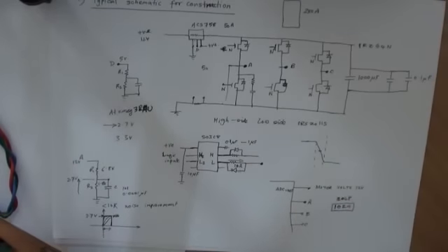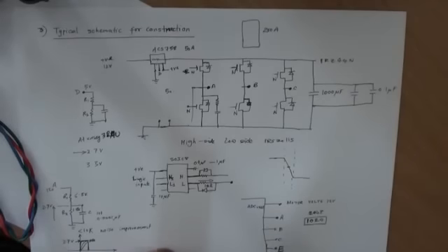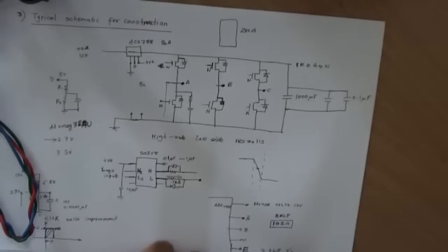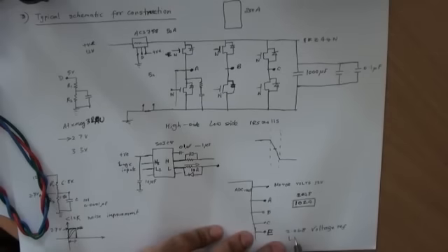So to do that, you basically want to introduce another known voltage source on a fourth analog input, let's call it E. You could choose something like a 2.048 volt constant voltage reference. From memory it's an LM4040, and there are different versions of them, so I have used the 2.048 volt version.